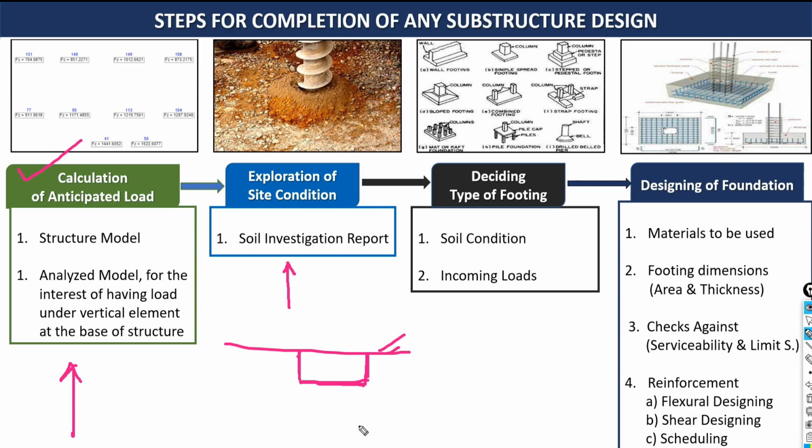As much as you explore your soil to a greater depth, you will get more information about the soil mass. But simultaneously the cost of investigation is going to increase. So, in equal proportion, the economy should not be disturbed, and you should get the required properties of your soil mass. Up to that, you need to go for the soil investigation.